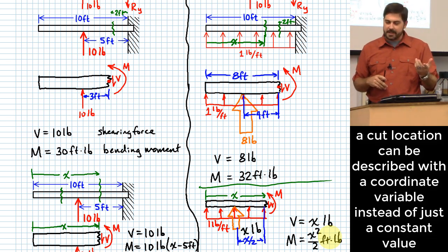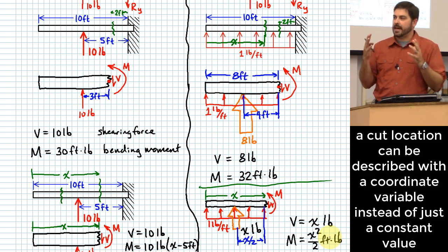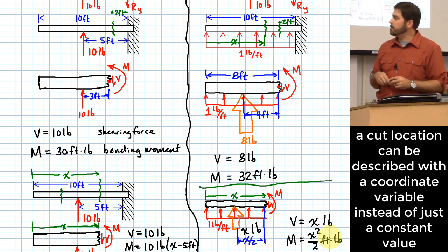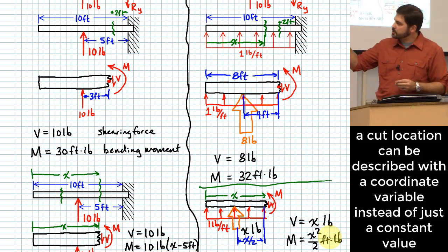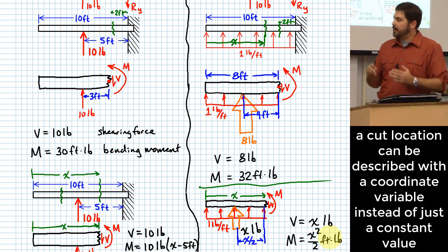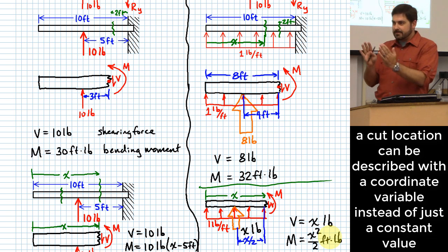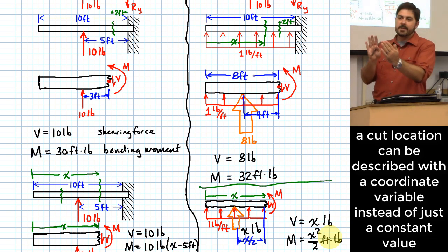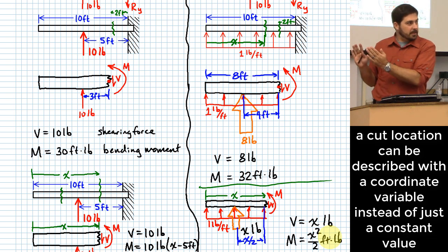One thing to say about that, though, in addition, is that you also have to keep in mind that with any concentrated loads or any sort of changes along the length of the beam, you might have to divide it up into segments, right? And say, this is a function that works in this segment. This is a function that works in this other segment.